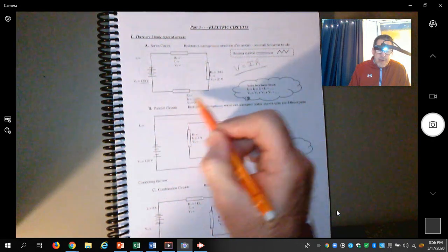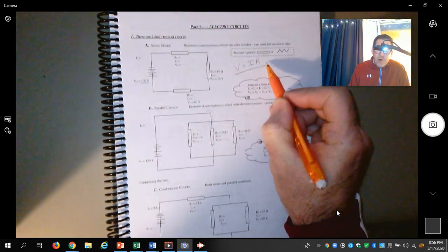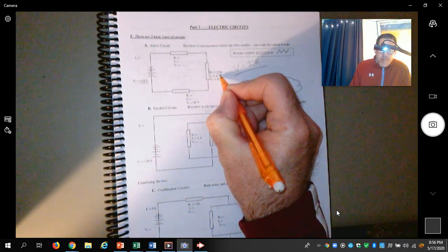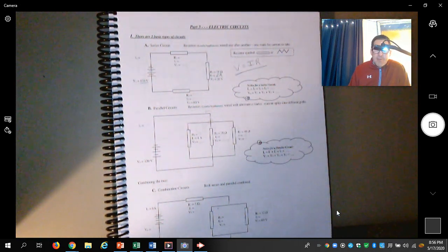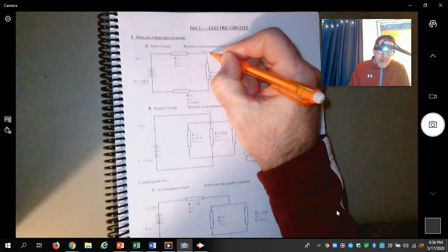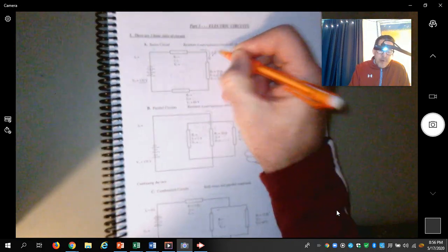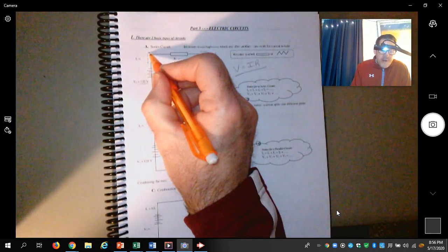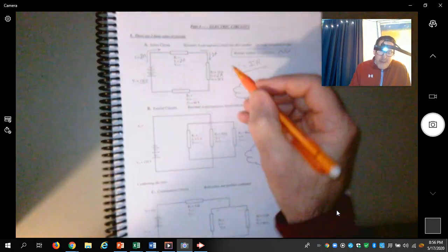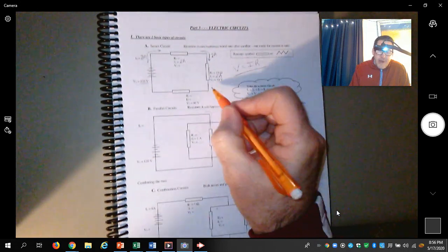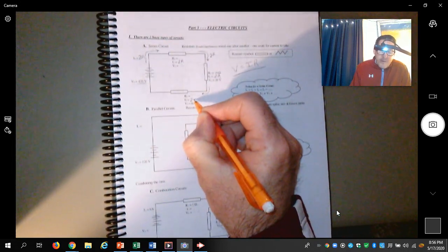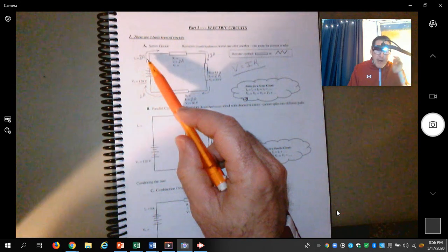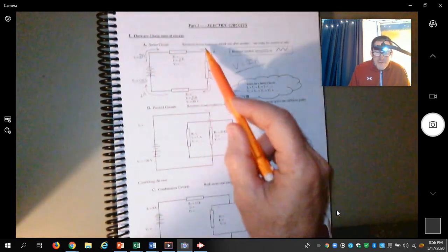I like to look at each resistor, and anytime I see two of three things, I can say VER and apply V equals IR to that circuit. If I apply V equals IR to that circuit, I'm going to get two cars, two automobiles, 2 amps that are driving through rest stop 2, which means two cars had to come this way into that rest stop, which means two cars must have come from the first rest stop or the first city, which means two cars had to enter into the first city. And those two cars, after they drive through this second rest stop or second city, are going to take another turn and drive right into the third rest stop. And those two cars are going to leave the third rest stop and go right back home. And that's great because the amount of cars that go on the trip, the current, has to be the same amount of cars that comes back home.